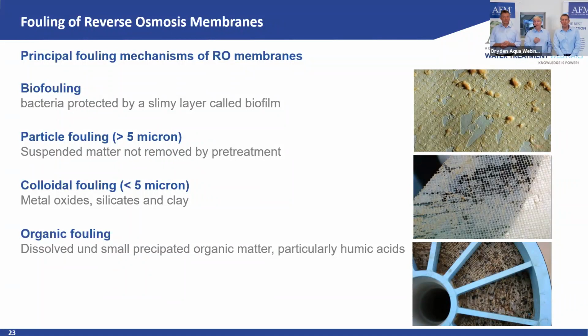They can be dissolved and precipitated. Typical humic acids, you need polyaluminium chloride to overcome the problem with humic acids, which are dissolved. But if you add some coagulant to it, we can remove it perfectly with filtration, even much better with AFM. Or free silica, right? With PAC, you make aluminum silicate, this you easily can remove. Exactly. Otherwise, we can't do it.